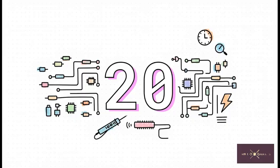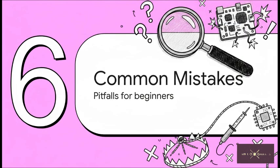Check out that number, 20. That is the number of tiny, fragile, extremely annoying surface mount components you just completely avoided unnecessarily removing, testing, and resoldering manually. By simply measuring the impedance of the paths to ground, you successfully isolated a complex motherboard fault in maybe 1 minute of diagnostic time? That right there is the true power of this technique, a real game changer. We're almost to the finish line.